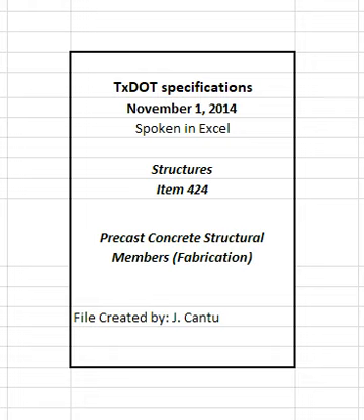4.3.1 Defects and breakage. Members that sustain damage or surface defects during fabrication, handling, storage, hauling, or erection are subject to review. Evaluate and repair members in accordance with the Concrete Repair Manual. Submit proposed deficiencies in accordance with the department's NCR guidelines and obtain approval before performing repairs. Repair work must re-establish the member's structural integrity, durability, and aesthetics to the satisfaction of the engineer.